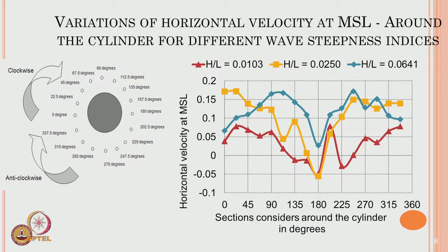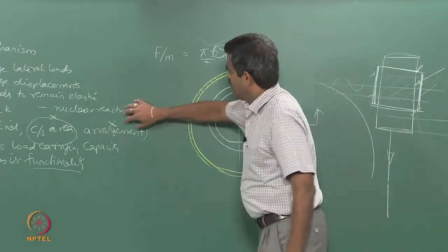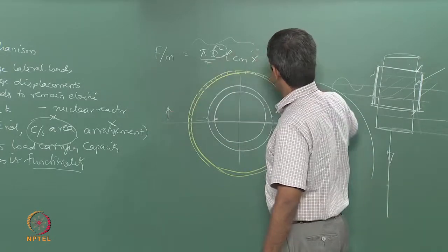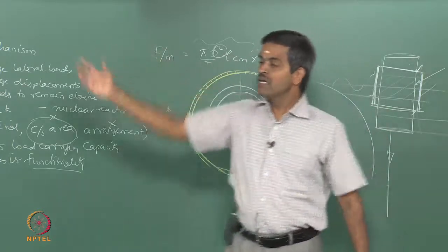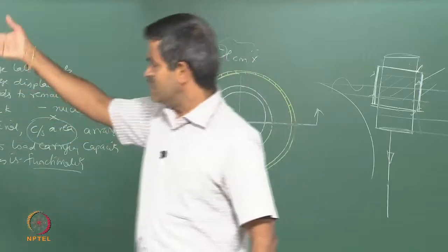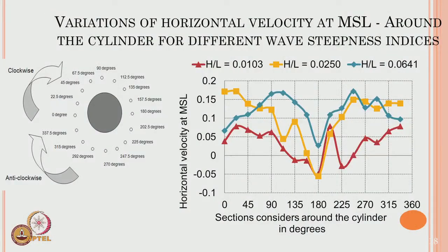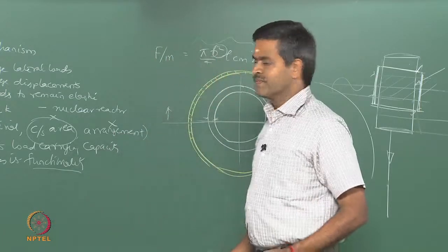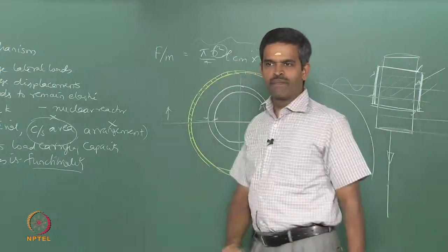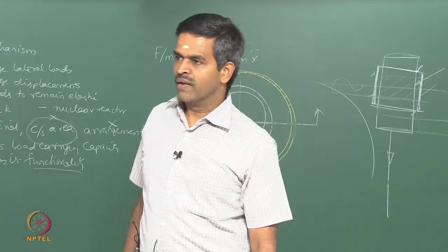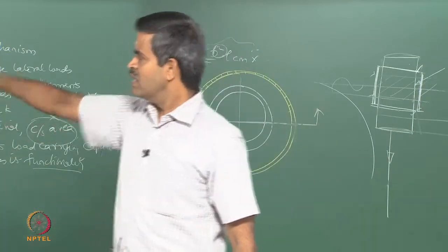So again, what would happen if the inflow field is dissipated, radiated, diffracted and rotates? So a circumferential study around the cylinder is also done for different angles varying from 0 to 90 both ways, and 180 until 270. So as it passes, what happens? You will see that the variation is maximum at 90, again dies down and again is maximum at minus 90. So these are the two segments where the reduction is becoming maximum. As it passes, the reduction is not there. That is the idea which has been verified by the circumferential study.